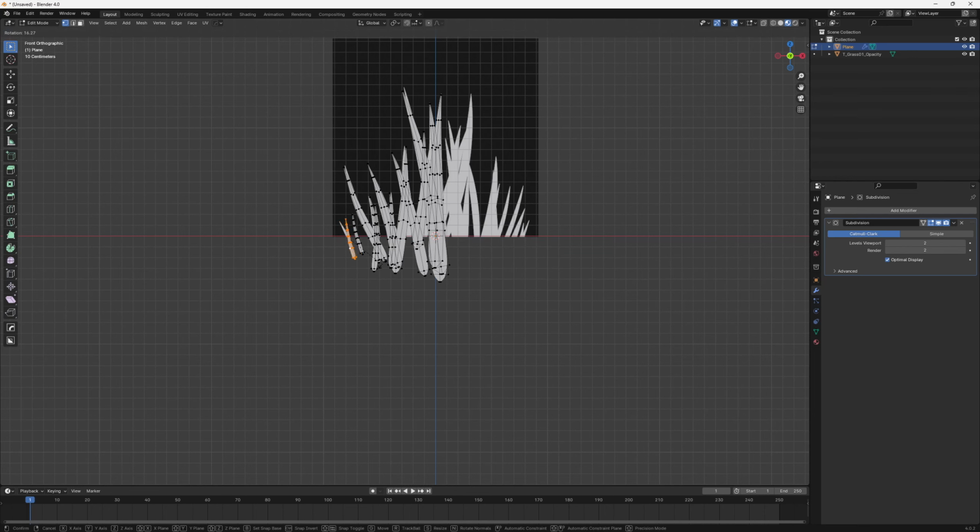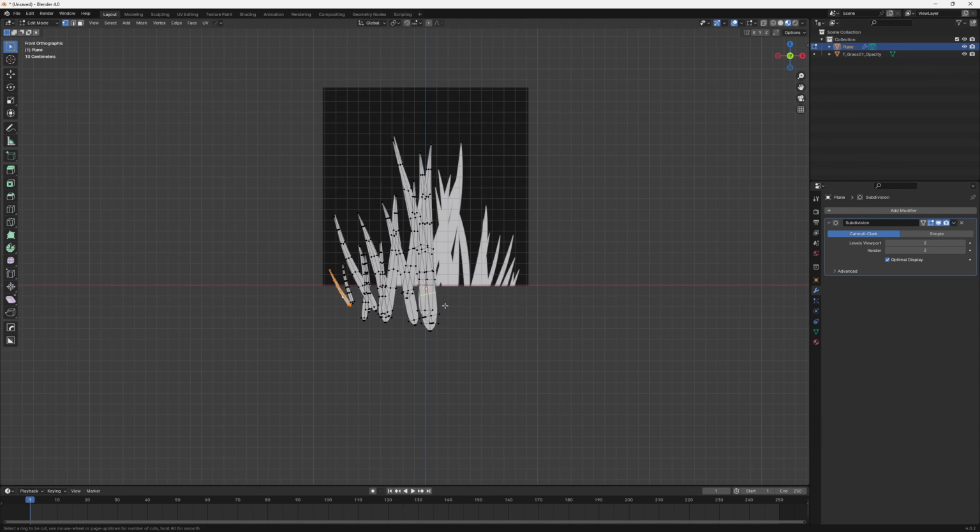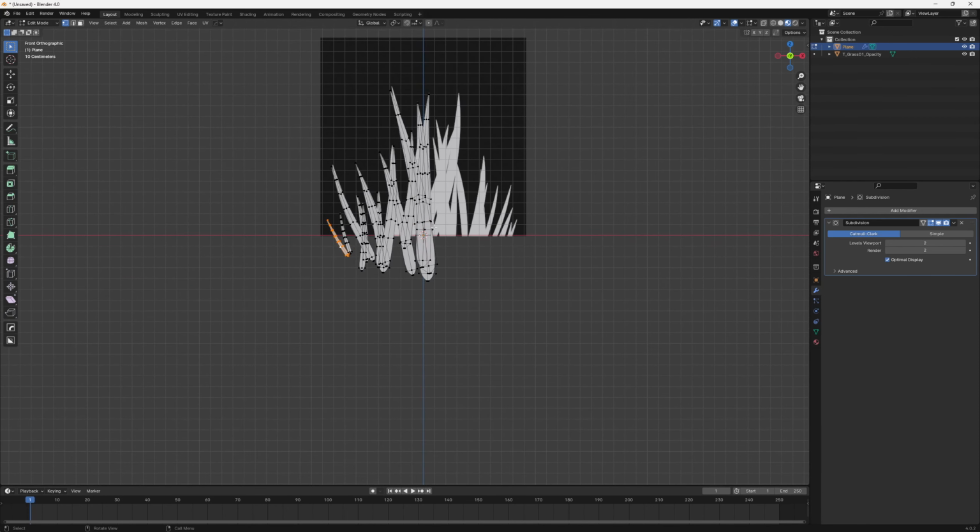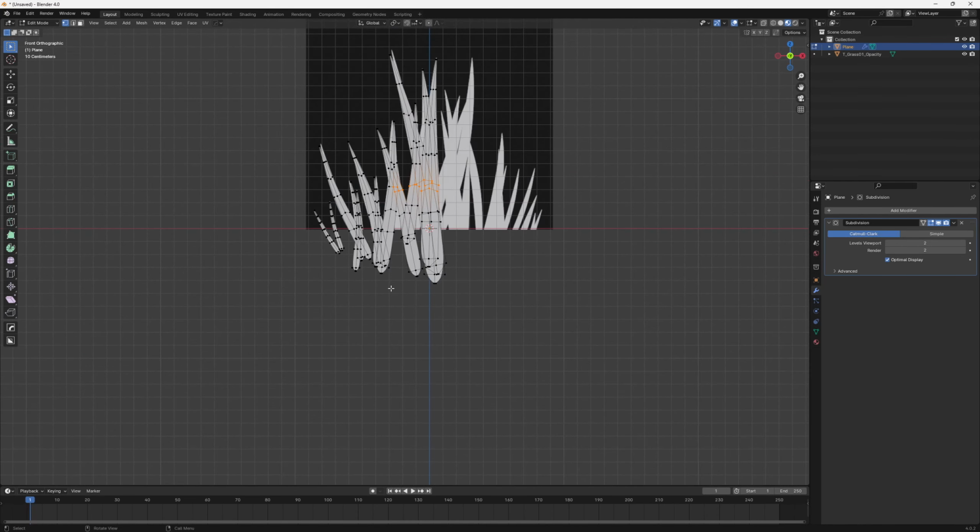So with this bendy grass, I wanted it to face the other way. I pressed S, X, -1. And that allowed me to rotate this with R. And I can match the curve of each blade. So there are only 3 elements when we're transforming all of these pieces in Blender. It is R for rotate, it is S for scale, and it is G for move. When I had added loop cuts, I used Control R, and when I had beveled it, I used Control B. And that should be the only modeling things that you would need to know for this video.